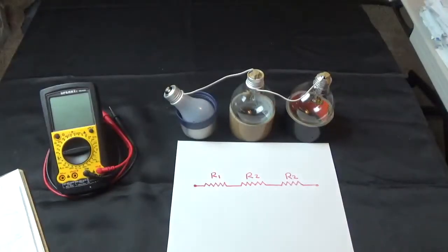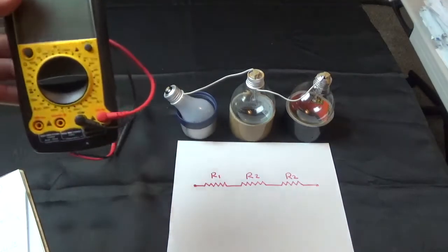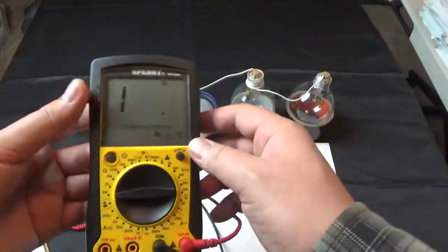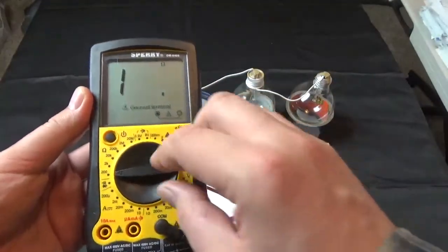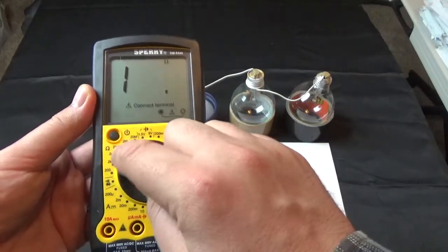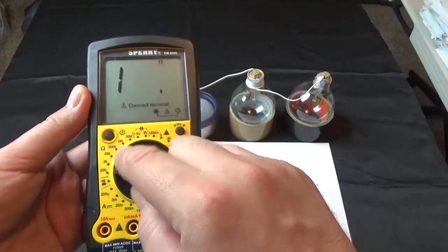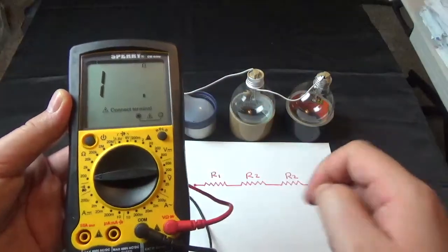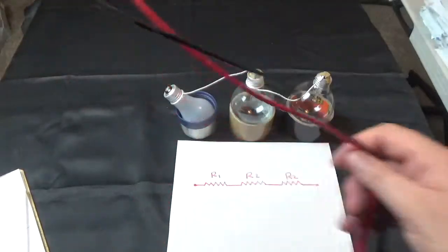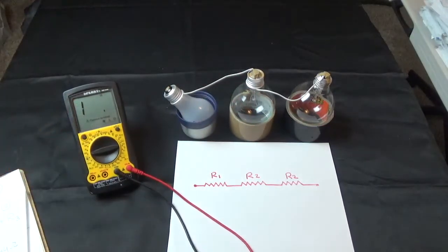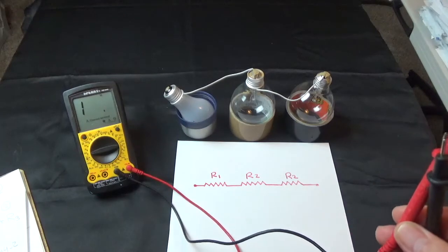So what we need to do, guys, we need to start the avometer or voltmeter, for example. So we start it, and then we need to go to the resistance range here, which is in ohms, and just keep it on 200, because the equivalent resistance shouldn't exceed 200.